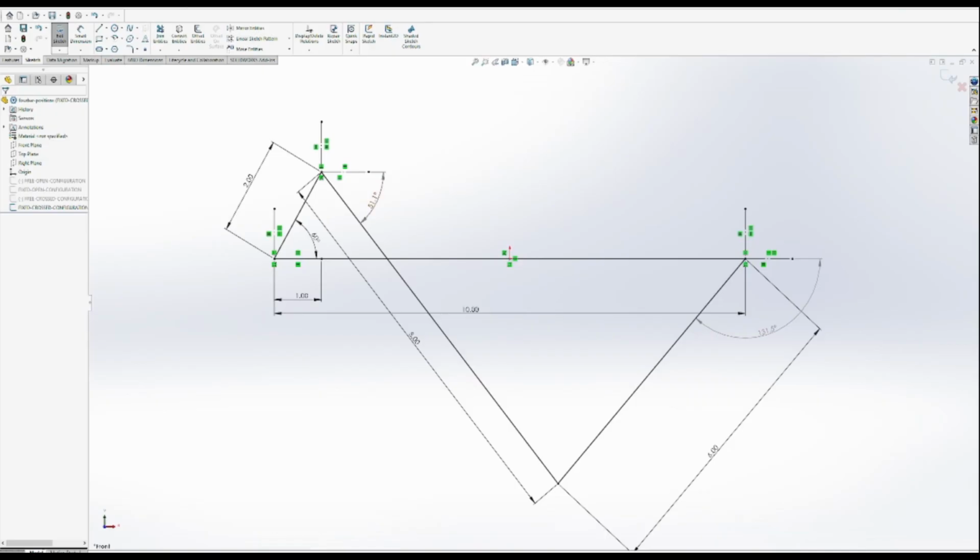And then for theta 4, we should be going negative 131.5 degrees, which again, we're going clockwise 131.5 degrees relative to the local coordinate axes. So this is negative 131.5. So negative 51.1 and negative 131.5. This is exactly what our parent equations predicted. So we are now again replicating the results for the cross configuration in SolidWorks as we predicted through our equations for a linkage of A 2 inches, B 8 inches, C 6 inches, and D 10 inches. Okay, so we have again proven that SolidWorks does replicate these position equations, which we would expect.